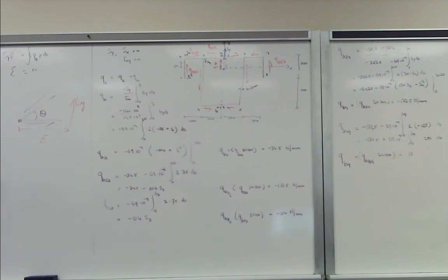So for the shear center, you always want to take a convenient point where all the shear flows go through, and that comes again with experience. You would immediately see, like you correctly stated, if I take the corner point, the shear flows will go through it. So the right hand side will be 0 by definition. Therefore, psi must be equal to 0. And that again comes with experience and just doing the problems over and over.